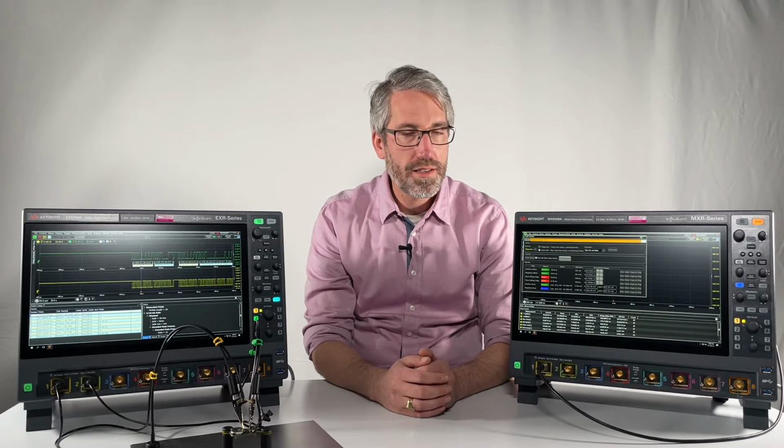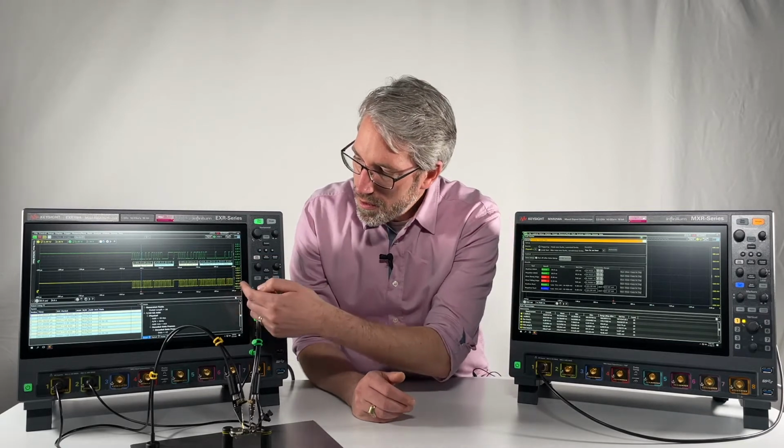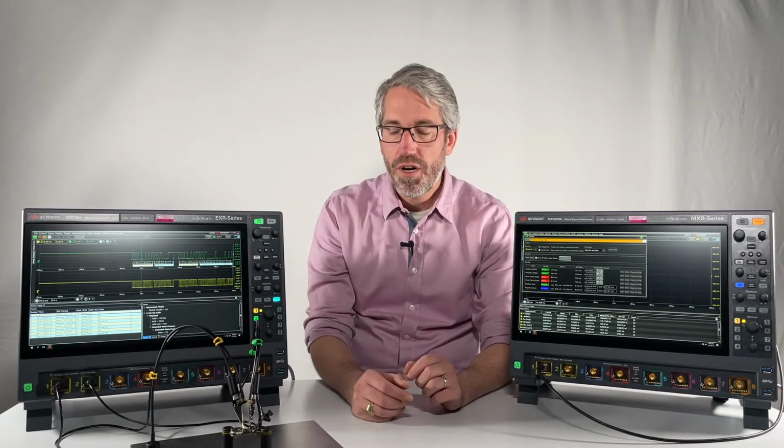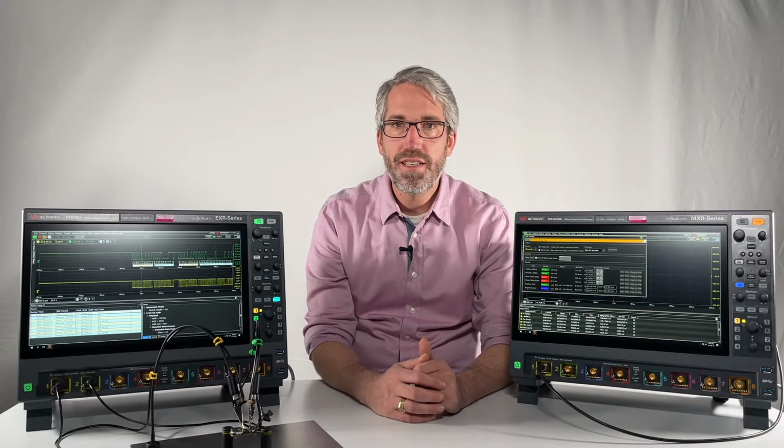Here, the ADC, or the analog to digital converter, is very important, as well as the noise performance of the analog front end. If you combine these two features, then you will get an oscilloscope with a high signal fidelity. This in essence means that the signal you see on the screen looks very much like the signal you're probing here. And you do not want your measurement device to deteriorate the measurement signal and the measurements themselves.